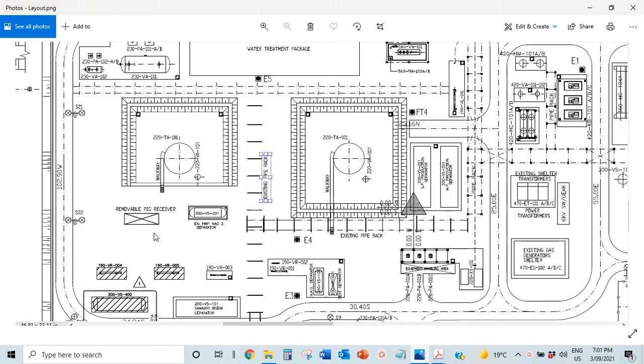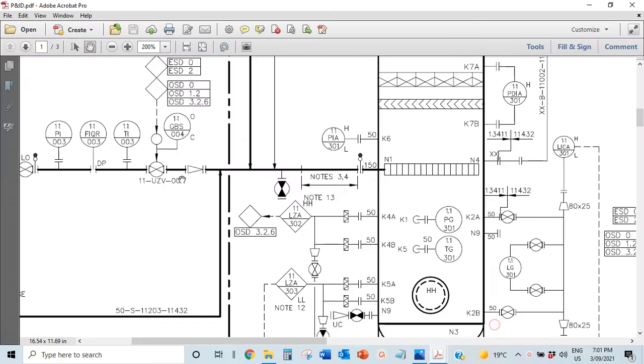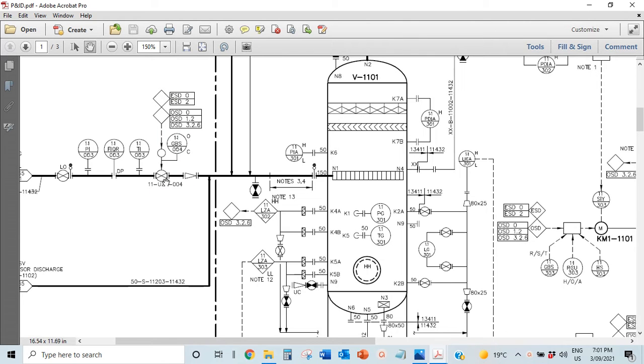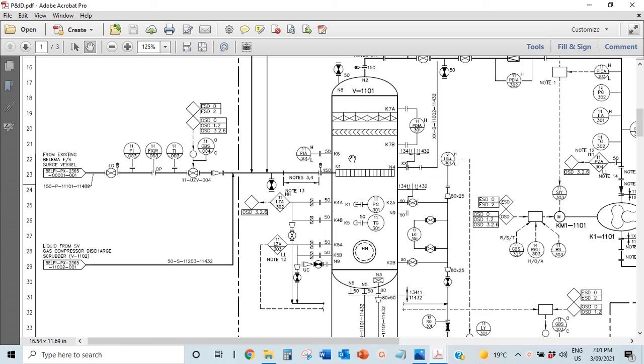So what you want to do is, the best way to stop a fire, because what we're going towards is fire and explosion risk assessment and quantitative risk assessment, is to close the feed of the fuel, whatever gas or fluid is coming into whatever vessel that's on fire. You want to make sure the shutdown valves close on the detection of the fire. So when they close, the fire is isolated. It cannot jump around. The fire should die out quickly once it doesn't see any fuel.